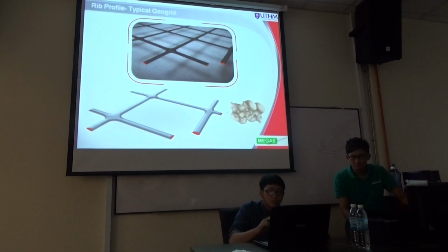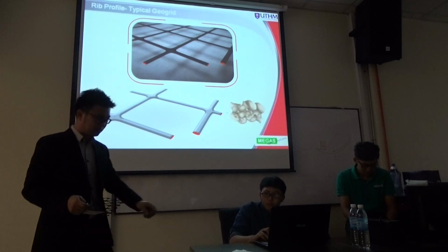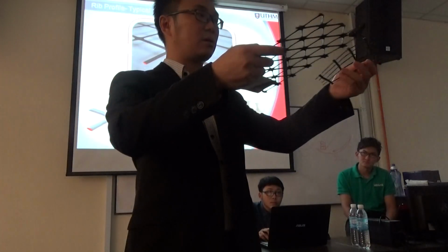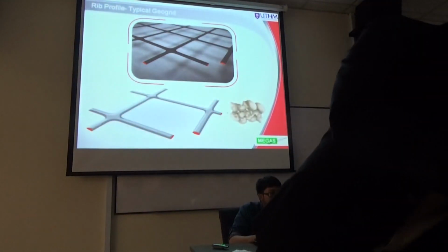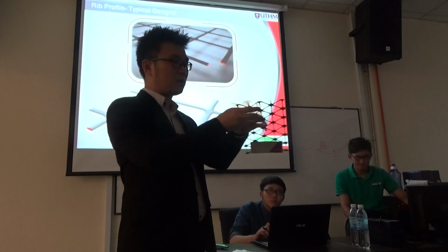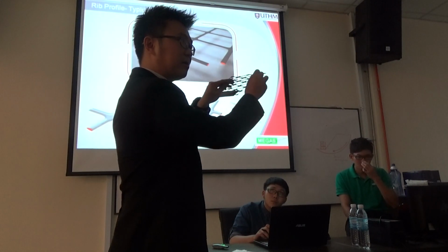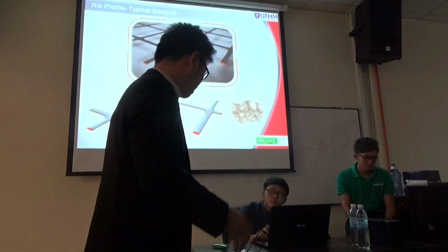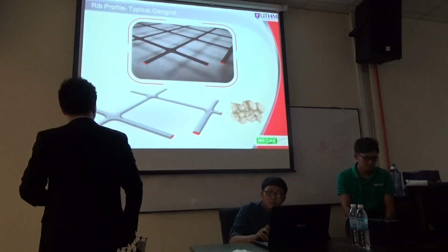So one of the very important features to form the interlocking mechanism on the geogrid is the rib profile. Okay? So the rib profile is concerned if you look at this grid and this grid. Okay? You can have a feel of this. This is actually a very flat type, it's almost flat. And this one, if you look, the rib, this one we call the rib, there's a thickness on the rib. Why the thickness is important, we can see on the following slides. Next.